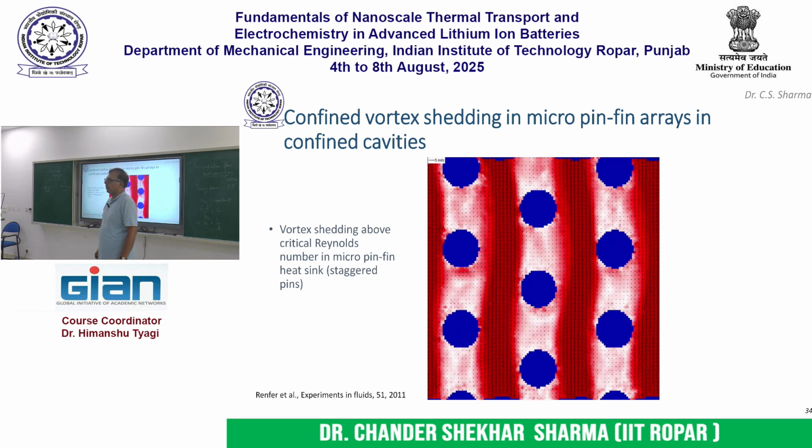Yes, just a little bit. There are many different configurations that have been tried, even staggered pin fins. Even the profiles of these pin fins have been looked at, whether they should be cylindrical or oval in shape. So many things have been looked at. But overall, this kind of configuration is able to provide more heat transfer for a given pressure drop when compared to a microchannel configuration. The disadvantage is that it is a bit more difficult to fabricate at the small scale.